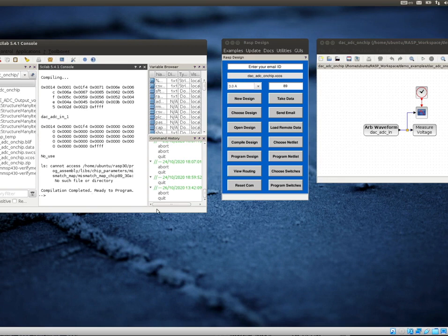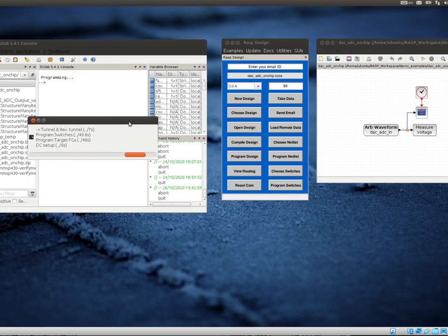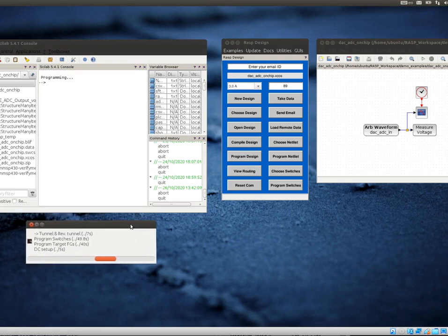At this point, I can now hit the Program Design button. And at that point, we can see what the program design is. Now, normally I wouldn't walk everyone through all the details of the design, but here it's kind of useful to see that we will end up having multiple aspects, one of which is erasing, which is what you talk about with tunneling and reverse tunneling. It'll then work on uploading the SRAM data, and then continue to program this. So we're running this in a verbose mode so you can see the details.